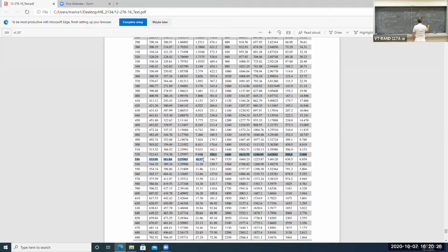And of course, U2, which is U evaluated at a reduced pressure of 9.84. There's internal energy, 374. 381, we're a little bit closer to the 374. So it looks to me like around 375, 76 kilojoules per kilogram.